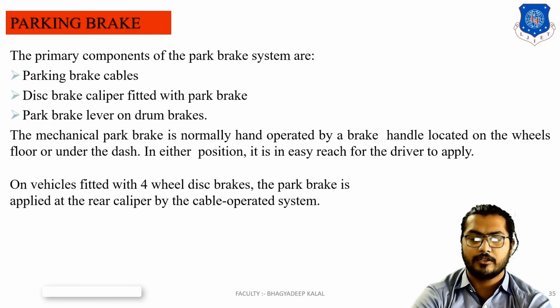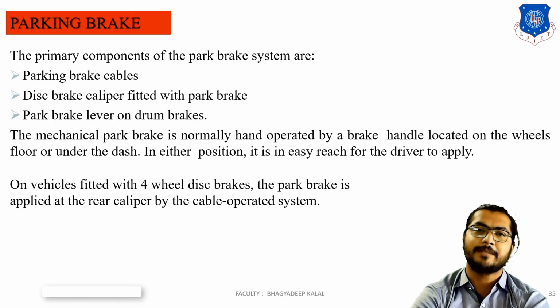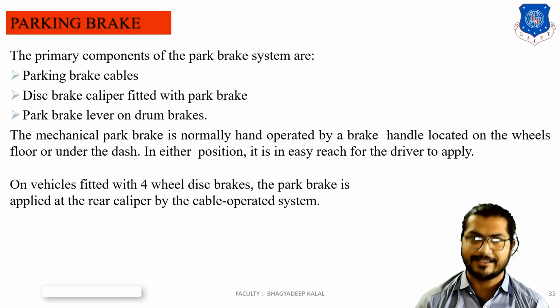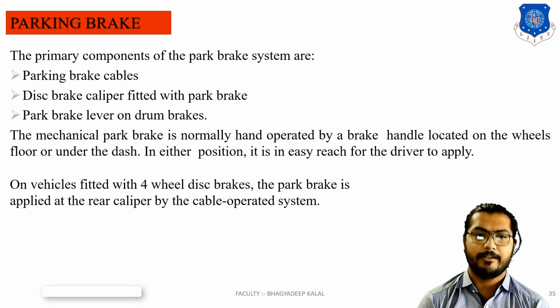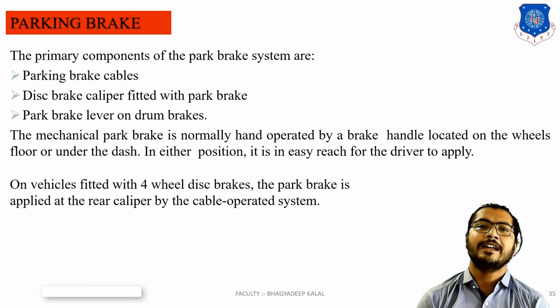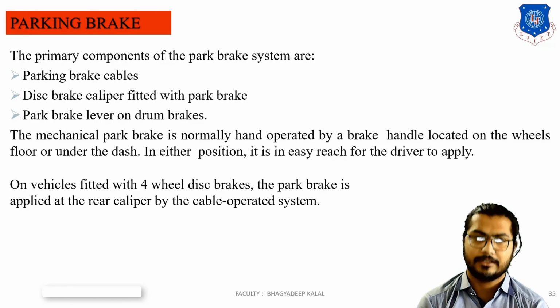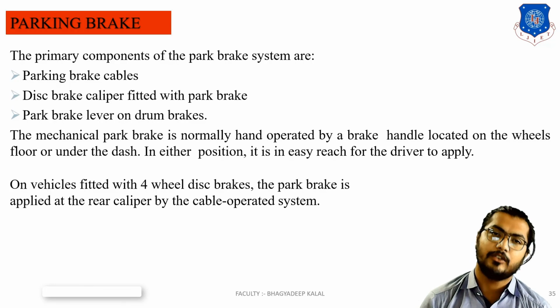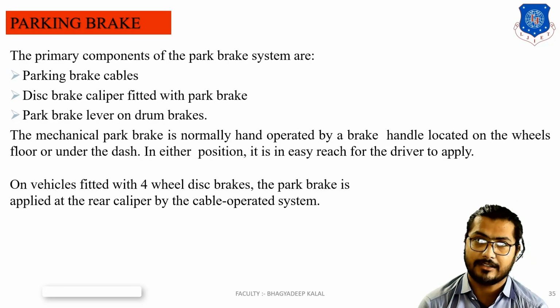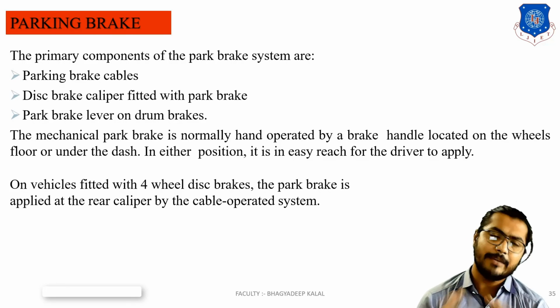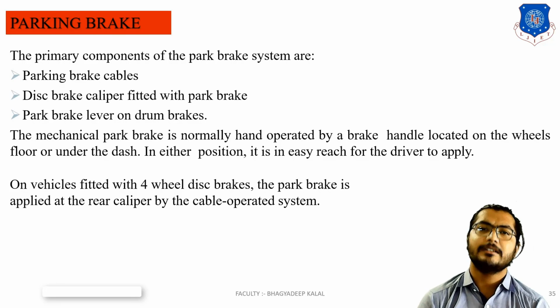It is not much more important, but sometimes it is asked for 2 to 3 marks from the exam point of view. So the parking brake is a manual brake or hand brake provided in vehicles, or we can say a secondary brake, operated by a cable, just like our cycle brake, which is connected to the rear wheel or either rear wheel side. One extra drum, or disc brake we can say, is provided. It is a manual brake applied by cables.